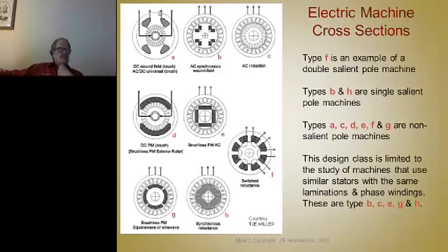So if you connect a DC power supply across here, you can vary the strength of this field and vary the whole torque speed curve and characteristics of the machine. But on the permanent magnet machine, you don't have near that flexibility because your magnetic field is fixed. It's not adjustable. You can't make it stronger or weaker.